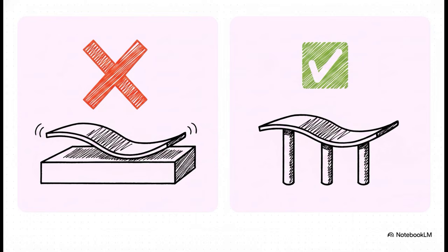One inspector presses down on the left side, the next inspector presses down on the right, and boom, they get totally different measurements. Now picture replacing that flat table with 3 specific target points, fixture pins acting as datum feature simulators. Which of these setups do you think is going to give you the exact same measurement every single time, no matter who's holding the calipers?